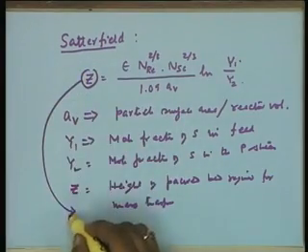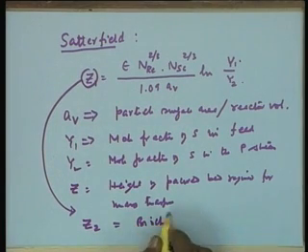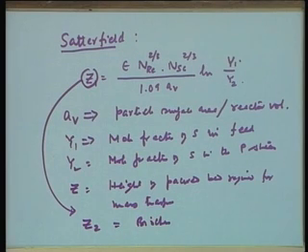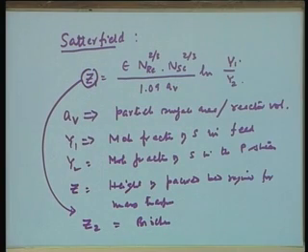and then compare it to the length of the reactor required for biochemical reaction. Let us say this is Z1, and you require Z2 based on biochemical reaction, if you just calculate the idealized reactor performance equation and calculate the height of the reactor required. Comparing the two values gives you an identification whether film diffusion is controlling or not, and essentially the one which is larger has to be used. So, for example, if this Z is much smaller than the height required for biochemical reaction, then you do not have to worry about diffusion. You simply design your reactor on the basis of biochemical reaction and be happy.